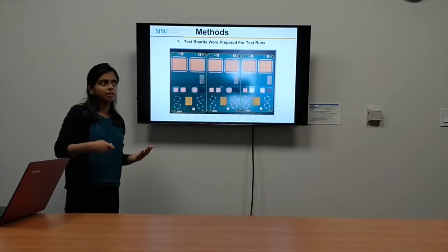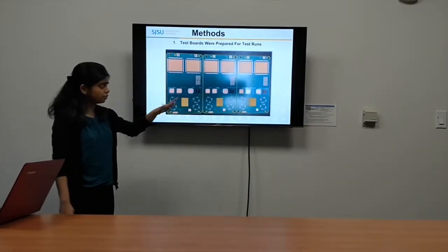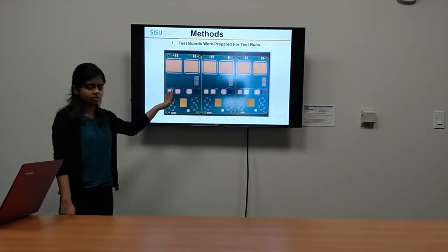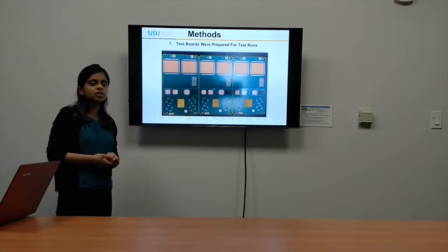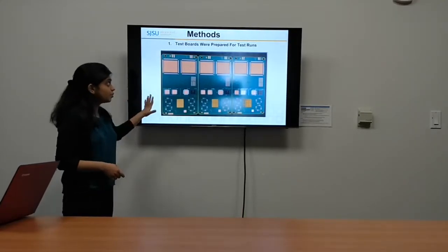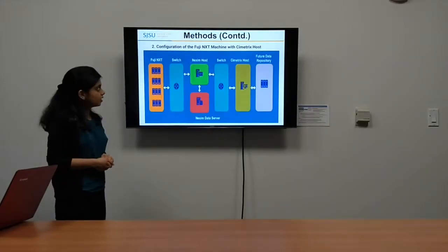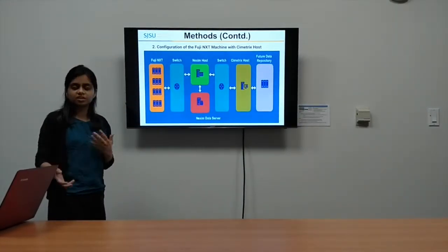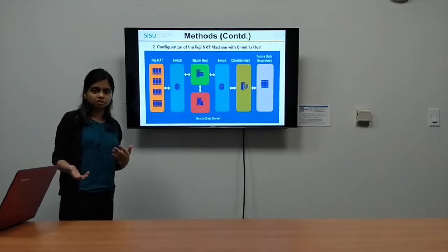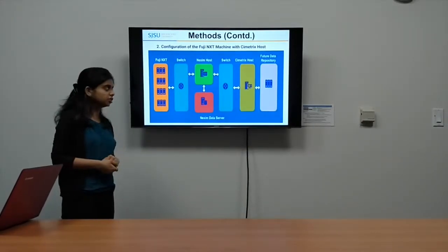Usually you would apply solder, right, to place the part on the printed circuit boards, but when you place it on the tape, there is a higher chance of inducing the errors. So we tape-ran the boards for the test runs that we were doing. Following this, these were put into the Fuji NXT pick and place machine that I was earlier explaining was the equipment that we used in this entire project.